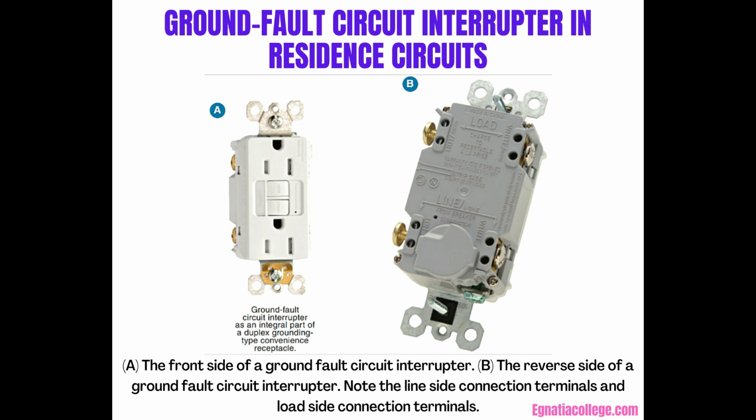Swimming pools also have special requirements for GFCI protection. These requirements are covered in Unit 22. Never ground a system neutral conductor except at the service equipment. Otherwise, the GFCI will be inoperative. Rule 10-210A. Never connect the neutral of one circuit to the neutral of another circuit.